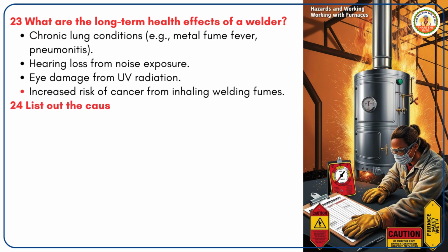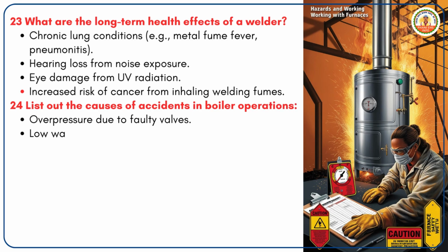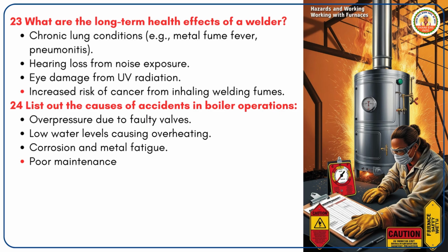24. List out the causes of accidents in boiler operations. Overpressure due to faulty valves. Low water levels causing overheating. Corrosion and metal fatigue. Poor maintenance and inspection practices.